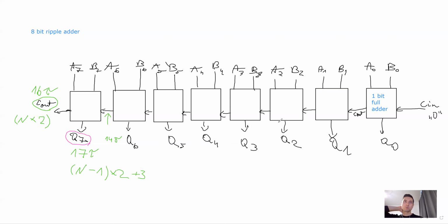But in today's computers, we have, you know, 64-bit architecture. What does it mean, a 64-bit architecture? Generally, it means how wide your arithmetic logic unit is, or how big numbers it can add in one clock cycle, which basically is how wide the addition part of the processor is. And I can just tell you right away, a 64-bit processor, of course, has a 64-bit adder, which basically consists of 64 one-bit adders chained in series, built in this way.